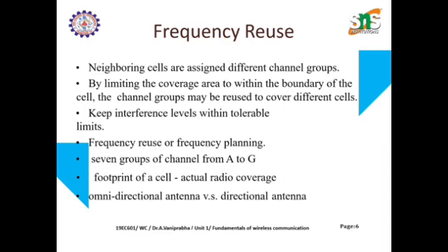Every cluster is formed of A, B, C, D, E, F, G. Since many clusters can be formed, it has to be taken care that there should not be any interference between the channels or bands. So there is a guideline to fix the frequency band in the neighboring cluster which is newly formed.